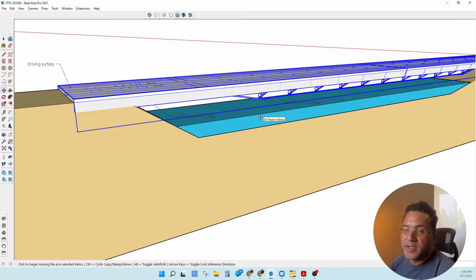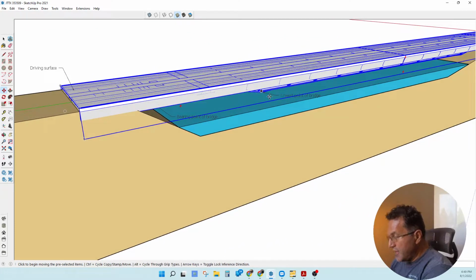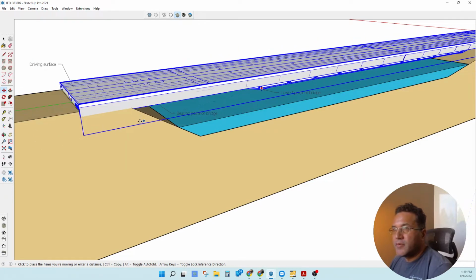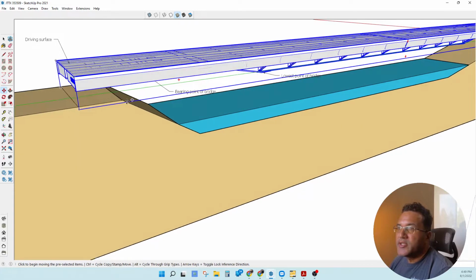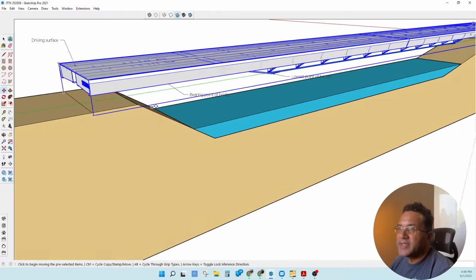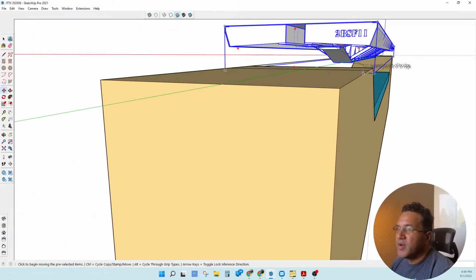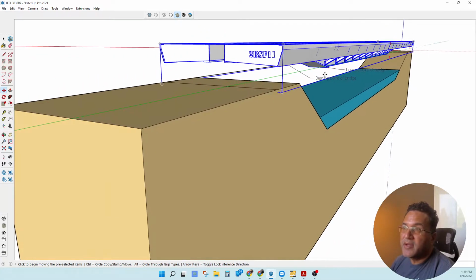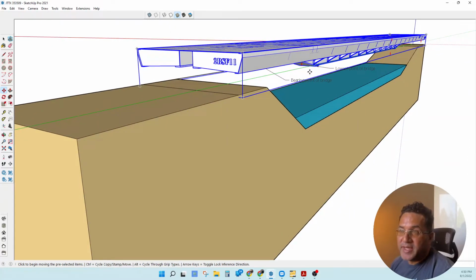Generally, most government agencies, they want the lowest point of the bridge out of the waterway completely. They want it way up over here. Okay, so the lowest point of the bridge is at the top of banks. Okay, it looked like this. You can see that now the bottommost part of the bridge is not lower, it's right at the top of the banks. Now we may have to put it an inch or two above that, but usually if we shoot for matching it up, that appeases your county or city requirements.